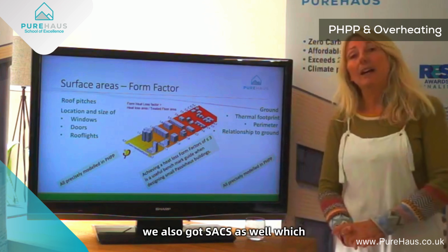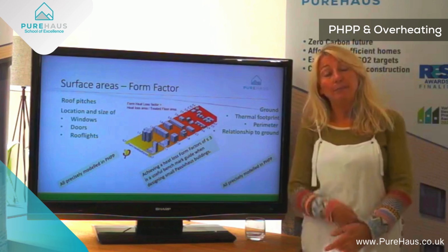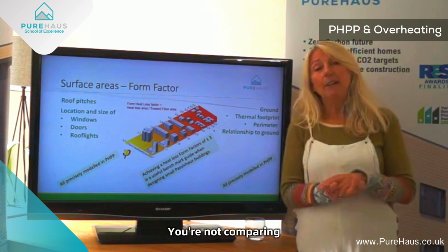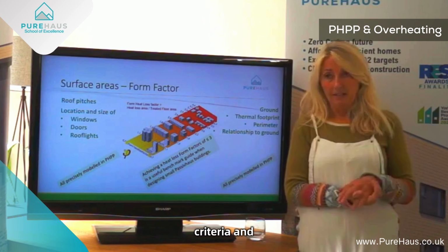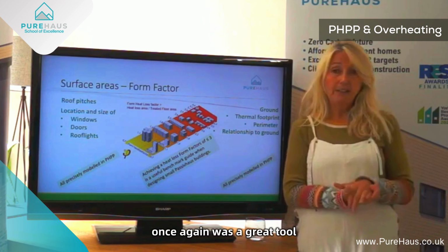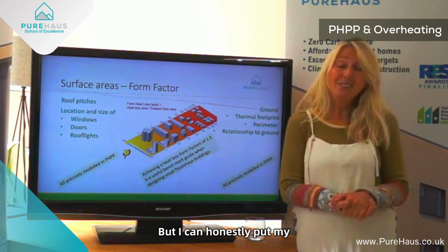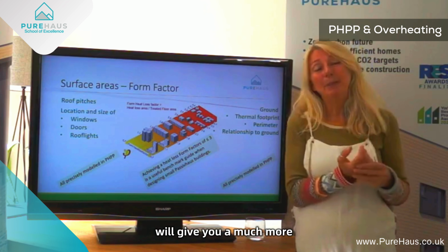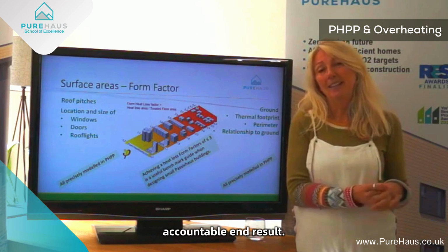We've also got SAP as well, which is usually a requirement of building regulations. You're not comparing apples with apples. SAP works on very different criteria, and once again was a great tool before the PHPP came along. But I can honestly put my hand on my heart and say that the PHPP will give you a much more accountable end result.